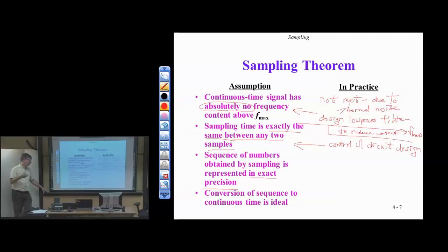That's a related issue because once we quantize, we can control the amount of distortion by how many bits we can capture off the analog amplitude. And then how do we represent that in a format, floating point or something? So that's a later consideration, but definitely one that we want to do when it comes to the full data converter that includes quantization. So this is all the A to D side. Right, this is all sort of the sampling side.